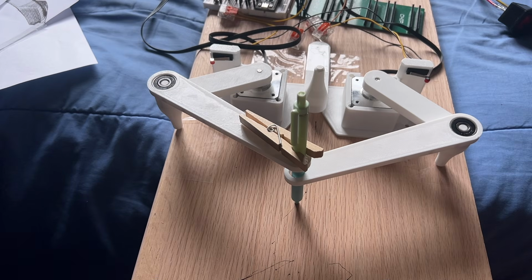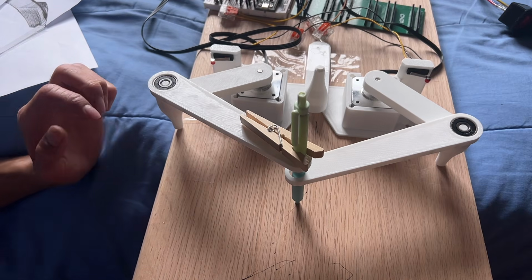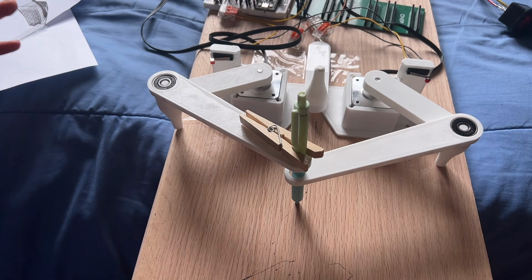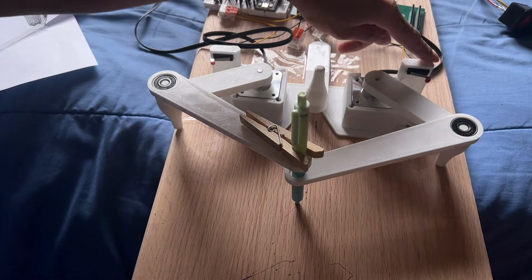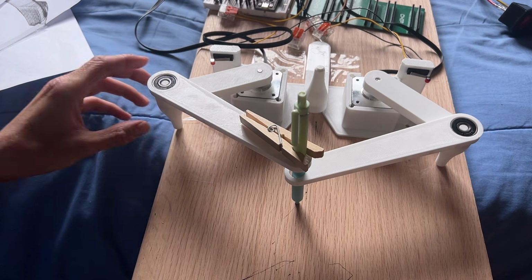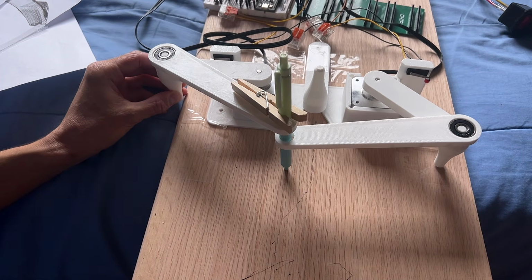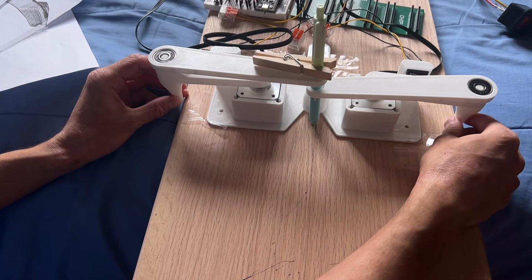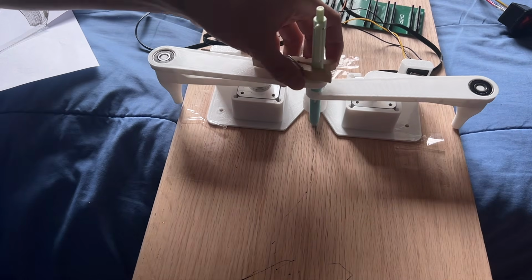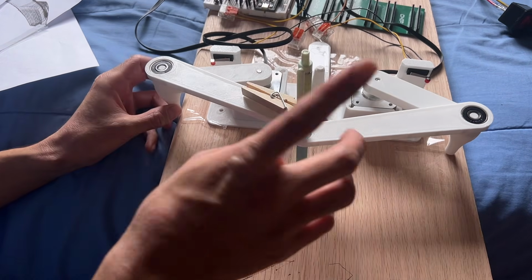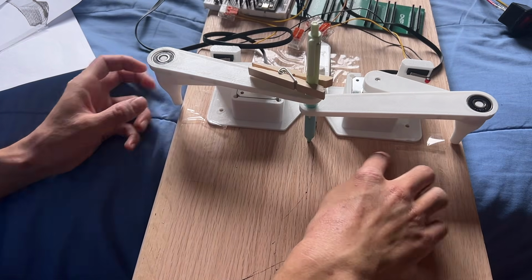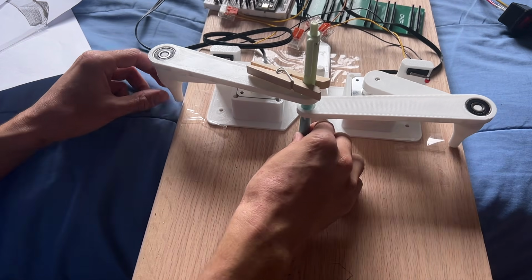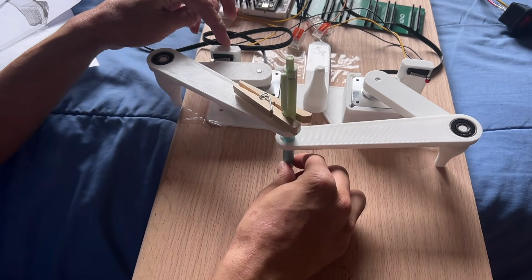So now that we've got the math problem sort of figured out, what I want to try to do now is make a new version of this and reposition a few things. Right now we have our limit switches right here, which is okay. It makes homing really easy. We know that this is going to be 0 degrees and that's going to be 180 degrees. However, as you can see, this thing is getting caught in the middle right there. And some angles, like angles close to this thing right here, we can't actually reach because of the limit switch